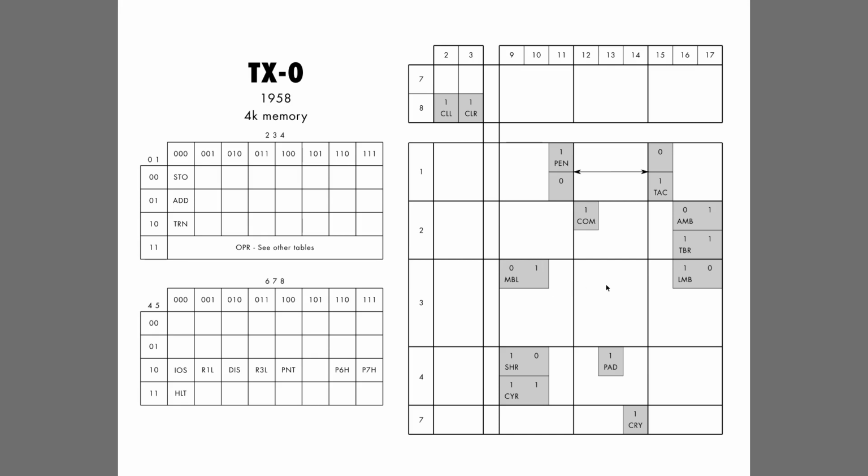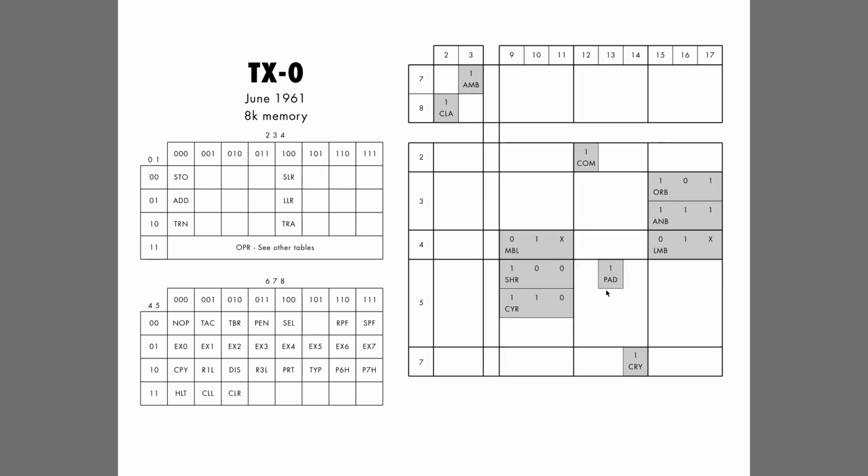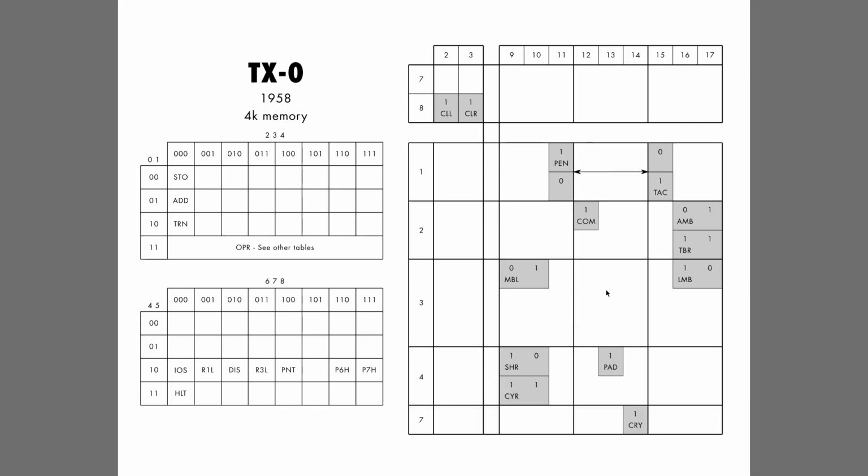And if maybe we want to have the accumulator cleared afterwards, we can just set the partial add bit, which does an XOR between MB and the accumulator. But because MB is still the same value as the accumulator, the result will be 0 in the accumulator, +0. So this is quite interesting and quite rich. And it was modified and expanded to some degree in the later incarnations, as you can see. Yeah, so let's next look into the I/O group.